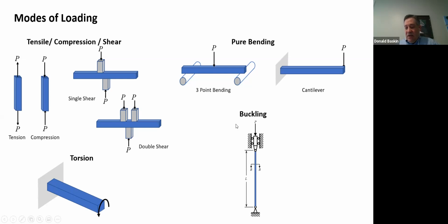Buckling is a local instability problem. You have a column that's under compression and maybe it's too thin and not stiff enough, and it collapses and fails and creates a real mess. For example, I once did a calculation on a glider that we were making out of composite material. You've got the wings coming out, and the back section with the tail, and there's a compression load there because of the way the thing flies. The propensity of the rear fuselage to buckle was always the limiting structural case. So buckling is very important.